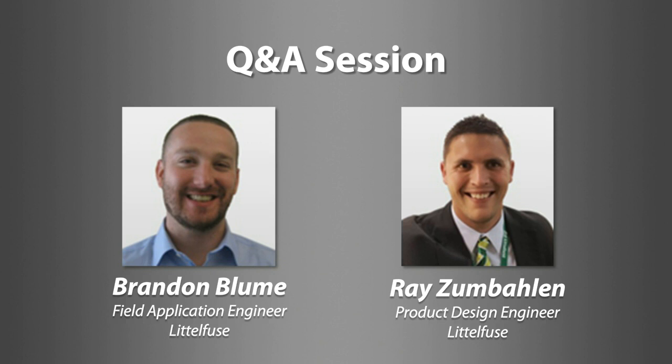And also, it depends on how often that fuse will see that pulse. If that's a one-time pulse, it's one thing. If it occurs every 30 minutes, it's another story. And those types of details are addressed in the high-speed application guide. But yes, in theory, that is what you would want to do, to ensure it's less than the melting I²t.